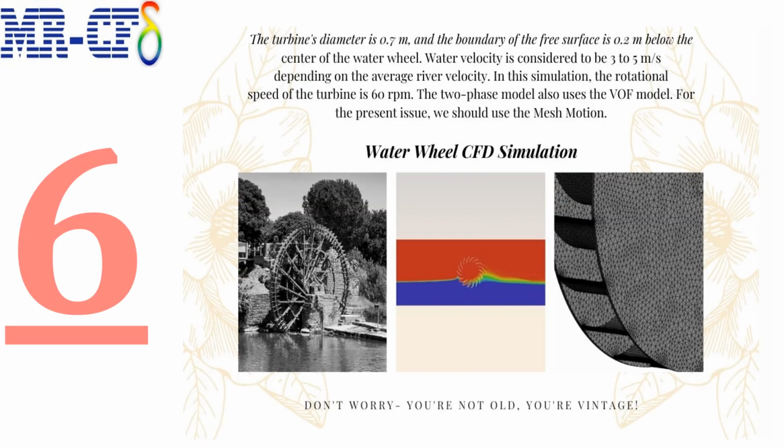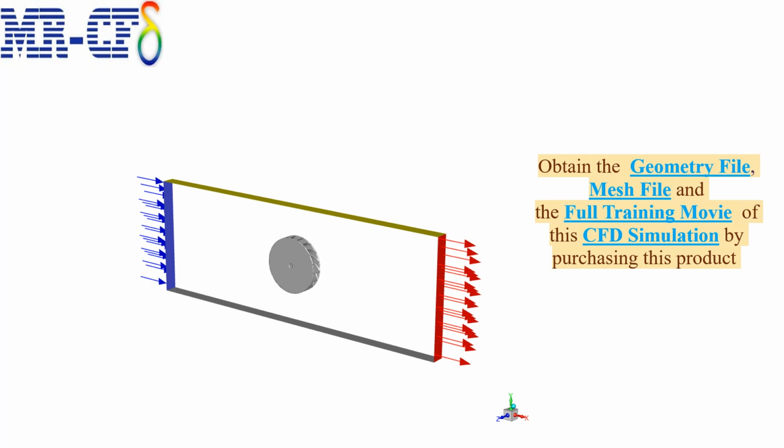In this project, we simulated the water wheel by ANSYS Fluent software. The geometry of the turbine is designed by SolidWorks software and divided into smaller sections to improve the geometry and mesh of the turbine. The geometry is divided into two general sections, rotary and stationary. The rotor part consists of a turbine and the cylinder that is located around the turbine, and the stationary part actually surrounds the rotary cylinder.